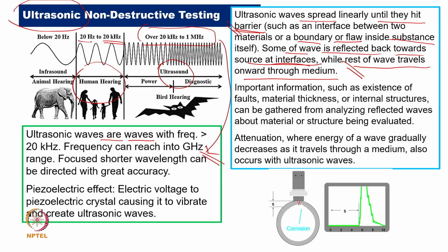We know that there is a discontinuity, something is wrong, and it needs to be looked into. If we have good know-how, we can really reproduce that kind of fault and show what is inside the surface. If we get waves, either transmitted or reflected, we can get information, such as the existence of a fault. It can also give information on the material thickness.